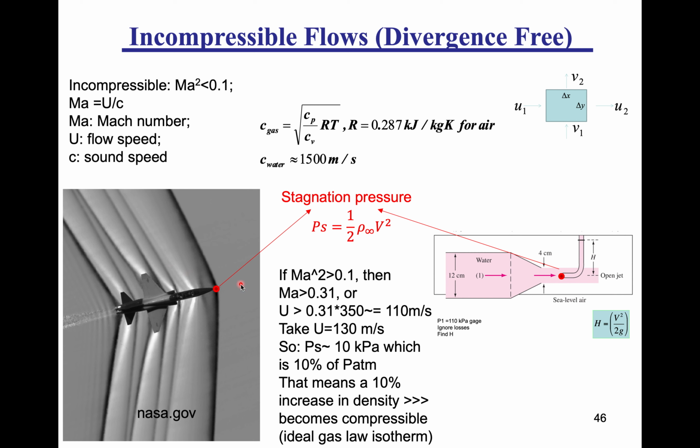But what happens when your aircraft is moving faster than the speed of sound is that the pressure information from the nose of the aircraft to where the particle is sitting doesn't get there in time. So the particle actually gets hit by this aircraft, and it wouldn't know that it's coming until after it has hit it. So this particle and this particle and this particle don't move out of place. They accumulate at the tip, and that's what we call a shockwave. It's an increase in density.